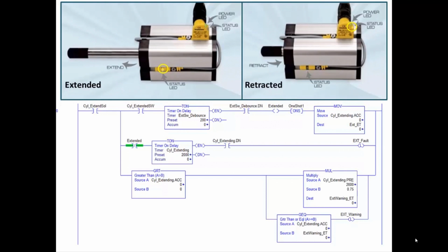And when you touch that indicator, it's a push button or a multi-state indicator, push button with multi-states, it says slow cylinder, you touch it and it takes you to the screen that shows all of the cylinders, and then you can identify which one was slow. Now, you don't have to stop the process, but you can keep an eye on that cylinder to see if something's bent, it's dirty, or sticky.